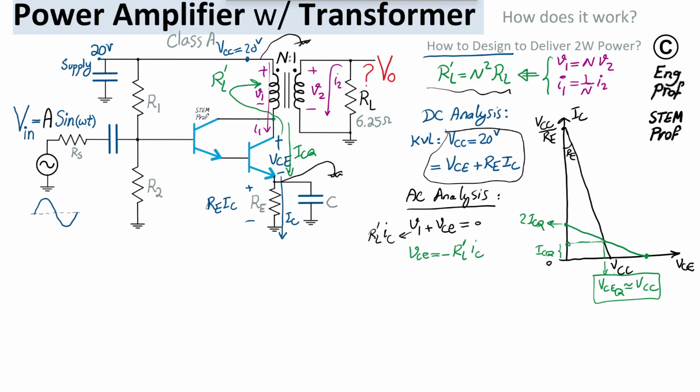Now during the AC, when the signal at input is doing the AC oscillation, the transistor would experience an AC current that in the maximum amount can counteract the DC current, basically resulting in the total current momentarily being equal to 0 when the AC current exactly cancels out the DC current in the best design.